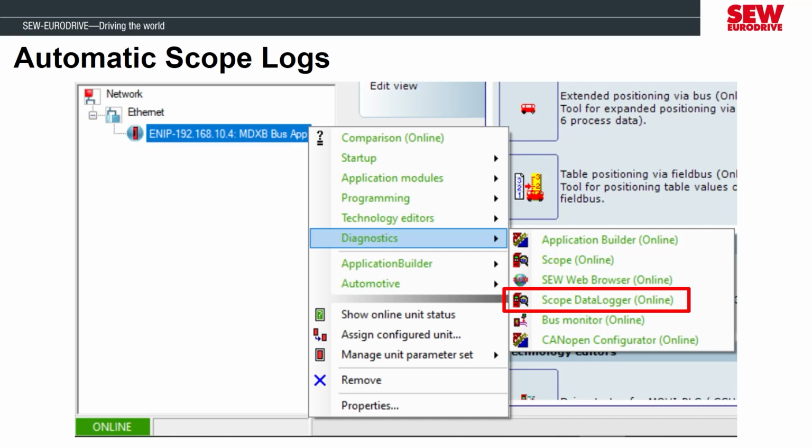recording before the fault is reset, because it is stored in volatile memory, and after the fault reset, the recording is deleted. With a data logger, if you leave a computer connected to the MOVIDRIVE with this tool running on the screen, it will automatically upload and store the scope files after the trigger event happens. It will then restart the scope to capture future faults.